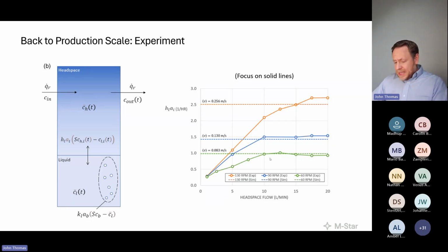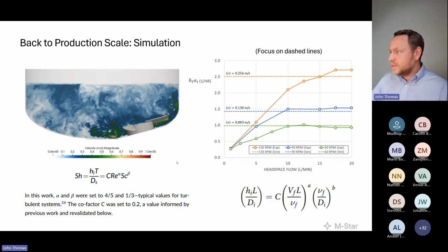But again, this is an important point. For any sort of mass transfer coefficient calculation, you've got to make sure that your driving potential is constant, or else you get this weird convolution down here, which can make for a head scratch. Like, again, look at this down here. How can you say that if I increase my impeller speed by 40%, my free surface transfer isn't changing? It makes no sense. What you're seeing here is the rate limiting effect of poor mixing in the headspace. So again, understand that, because it matters when trying to predict this transfer rate.